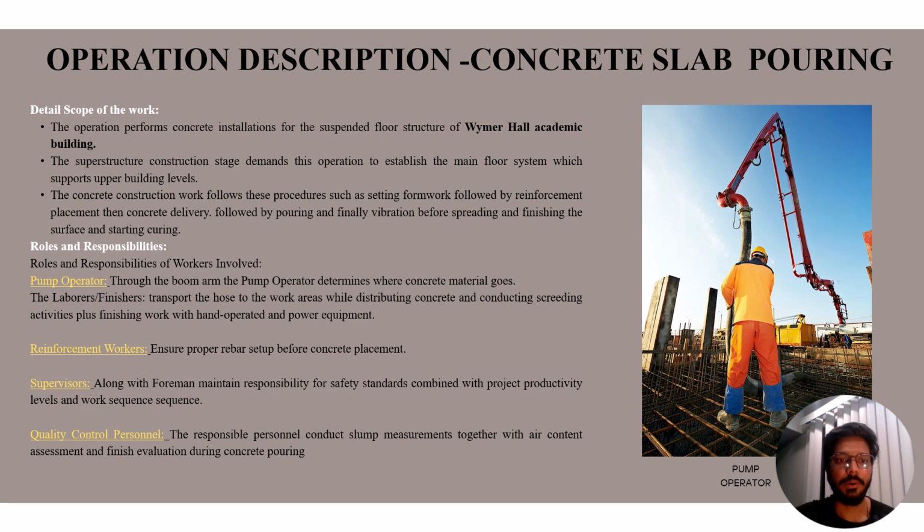Then talking about the last stage, which is quality control. After doing all the things like pouring the concrete, curing and vibrating it, the quality should be maintained throughout, and that's the responsible personnel we have. He conducted a slump measurement with air content and finishes of it.